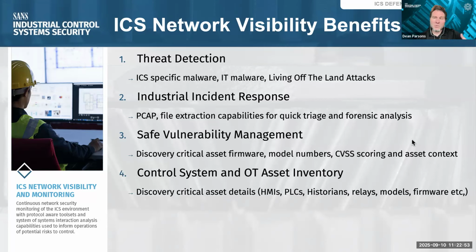Number four is because we know the assets that are communicating, we now can build an asset inventory, an OT asset inventory. So your targeted devices and control systems, PLCs, HMIs, historians, protection control relays, all of those devices will be seen if you're looking in the right place, and you can now detect information about the models and the firmware version, as we mentioned before, not from a vulnerability perspective but an asset inventory perspective. That can be married up with number three and threat intelligence from before.